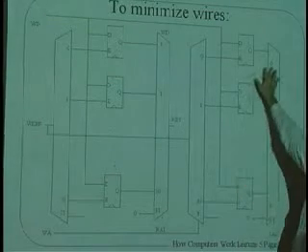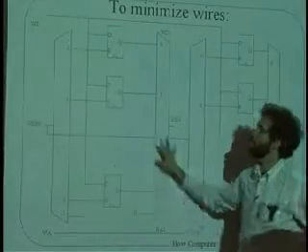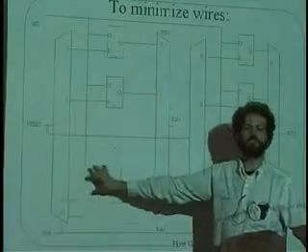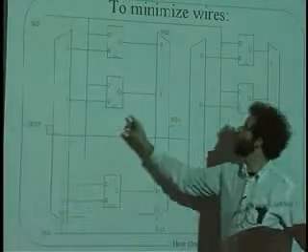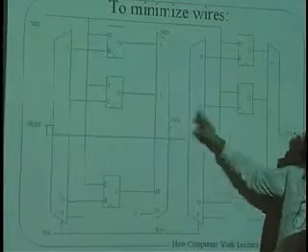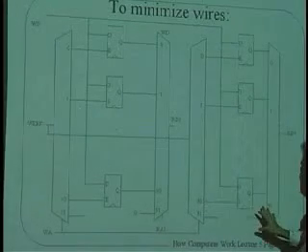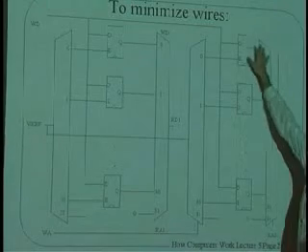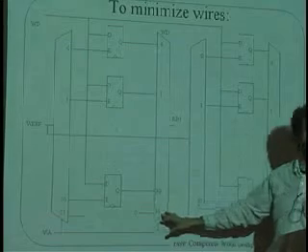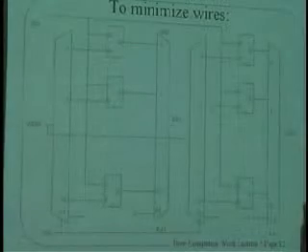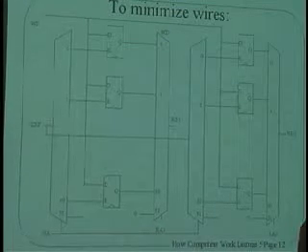In other words, this register file over here on the right is exactly the same as this register file over here on the left. Each of the register files has one write port, just like we had before, and only one read port. Now this is small enough that we can fit this entire thing on a single chip, and the thing on the left being exactly the same as a second chip. And now when we look at the two halves, how do we keep the two registers in sync with each other?